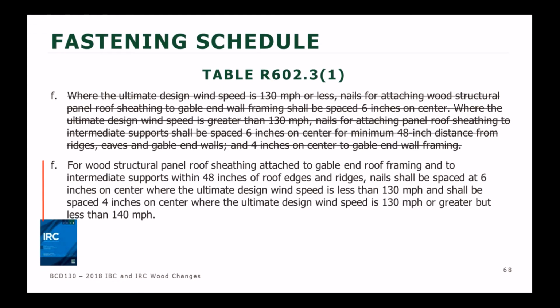And there again, we have just sort of showing where the text looked like previously to what the text looks like now. It was a clarification of it. And just to try to emphasize that 4 inches on center occurring. Many people didn't even know that this provision was hidden in the fastening schedule table. So hopefully now that's a little more clear, and it shows that you need to go back 4 feet with that tighter nail spacing.